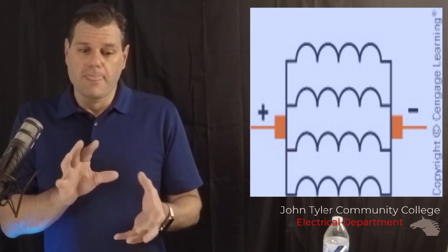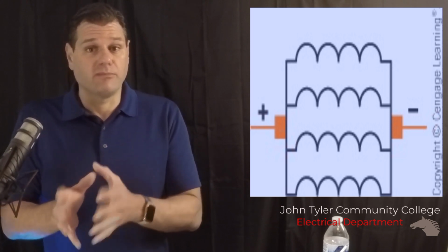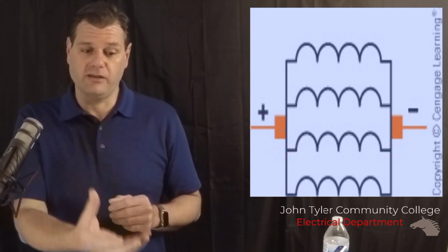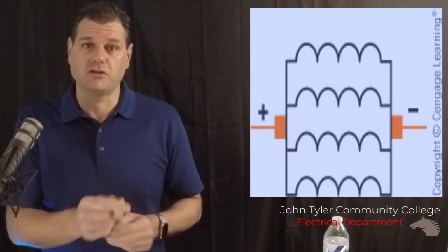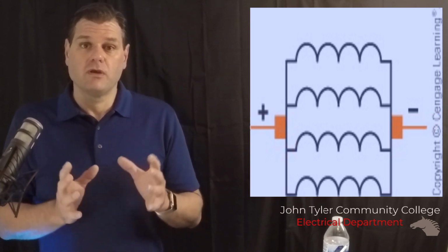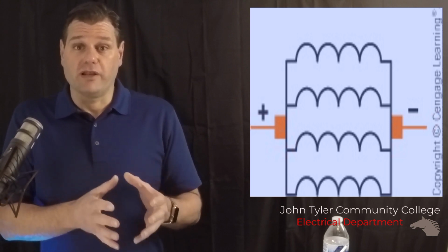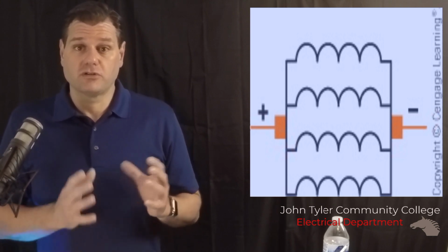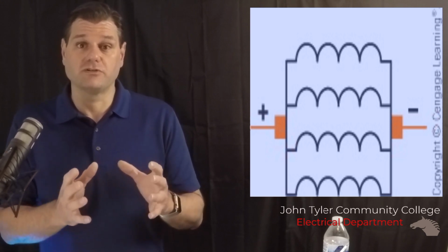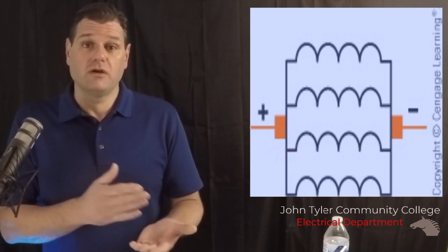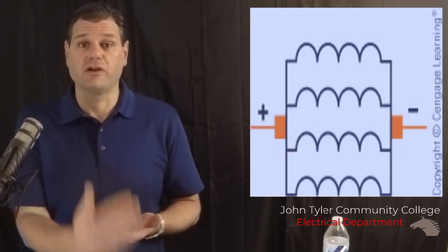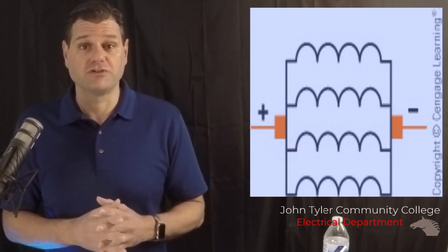The armatures in a generator and motor are pretty similar, almost exact. If you add electrical energy, you get mechanical rotation. If you add mechanical rotation, you get electrical energy. The same device. This type of winding is used for something like a car starter. Low voltage, 12 volts, but hundreds and hundreds of amps to crank and start your car. This type of generator would produce a low voltage but very, very high current, so you can do a lot of work with it, a lot of energy.